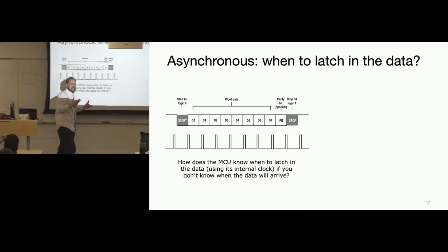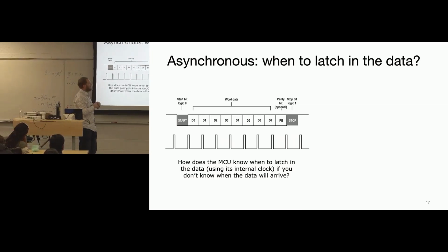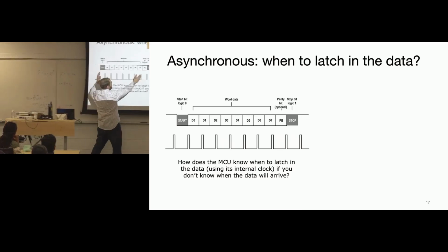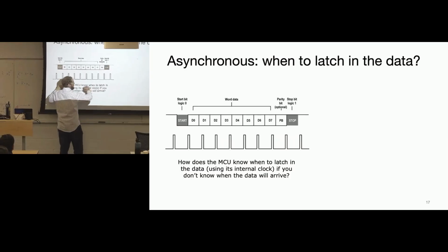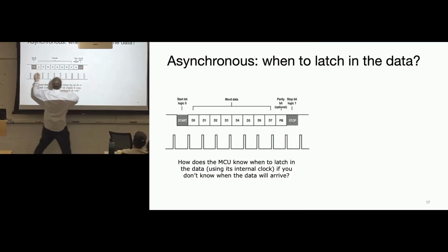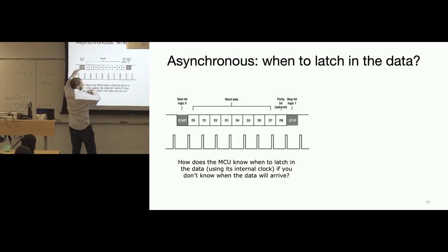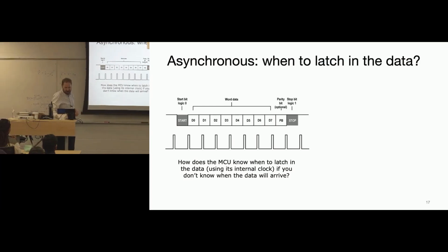So this clock error will happen in your baud rate, partly because the source clock you have may not be perfectly divisible into your baud rate. It might be an approximation, or the transmitter might not have a perfect delineation to be fully accurate in the baud rate. So this is only really good for 8 to 10 bits worth of data, and then on every single frame, you're going to calculate when to start looking based on this transition. Because of clock skew between these two domains, you can't rely on this timing all the time. But when do you go and figure this out?